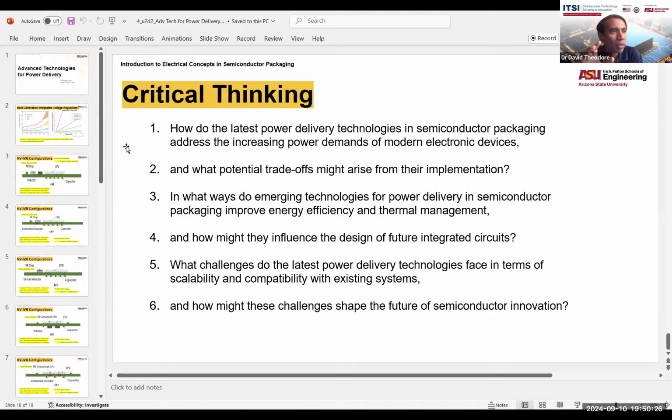Again, with all of those, the drive is to make the actual design smaller with fewer components and to increase the stability of the VR. So there are several things that we need to do. We need to be able to bring in a higher voltage and get that higher voltage as close to the devices as possible, which means that the high voltage needs to be stepped down to a low voltage as close to the devices on the chip as possible.